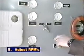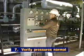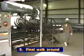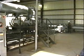Now adjust RPMs to the desired level and place the engine back in automatic speed control. Verify that all interstage and discharge pressures are normal. Then take a final walk around the unit to ensure that there are no gas leaks, unusual noises, or abnormal vibration. Now, in order to shut down this type of package, this is the recommended sequence.